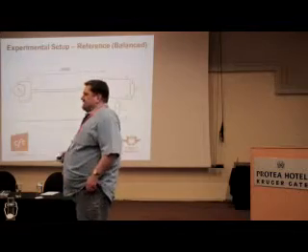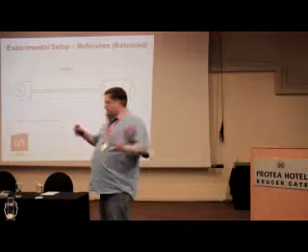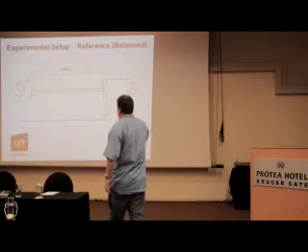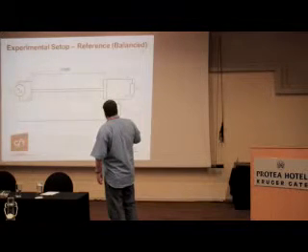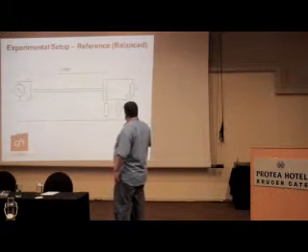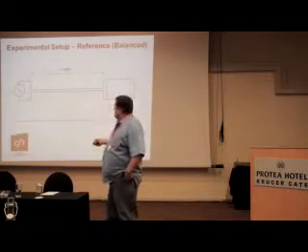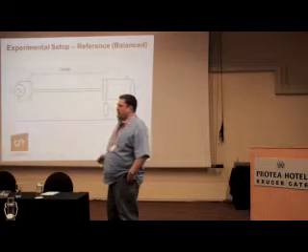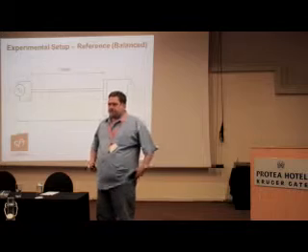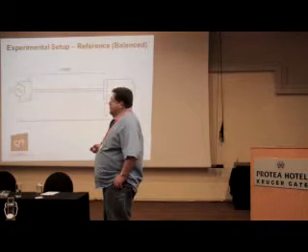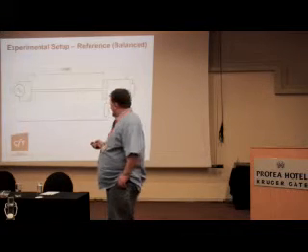The experimental setup that we used was a piece of wire, just 3 wires. There's a live and a neutral wire that come down, and we've got a 50 ohm load here, 50 ohms down to an earth wire. The interesting thing that we did was we didn't connect the earth wire at all. The earth wire was floating in the air. And what did we see when we started measuring the transfer function of this channel?